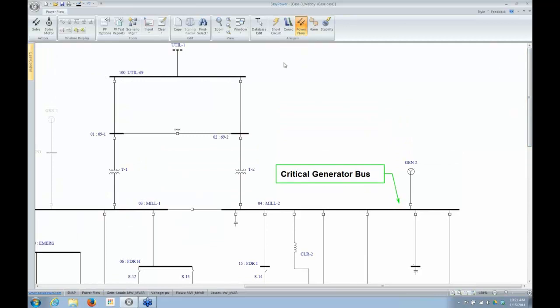One of the things that we need to deal with in PowerFlow that we don't have to worry about for short circuit or some of the other analysis, arc flash, is the way that we model the sources in terms of PowerFlow. So when the PowerFlow engine is doing its iterations, it's trying to balance out all of these watts and vars in the system.